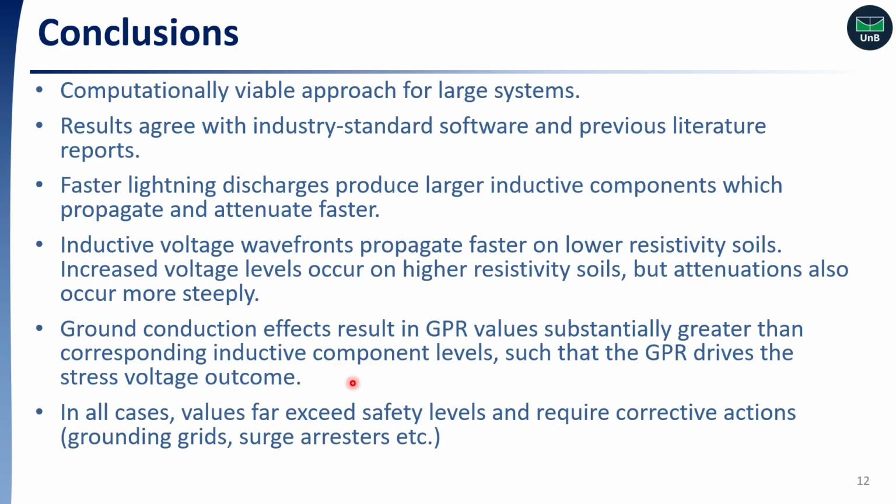Ground conduction effects result in GPR values substantially greater than corresponding inductive component levels, such that the GPR drives the stress voltage outcome. In all cases, values far exceed safety levels and require corrective actions.